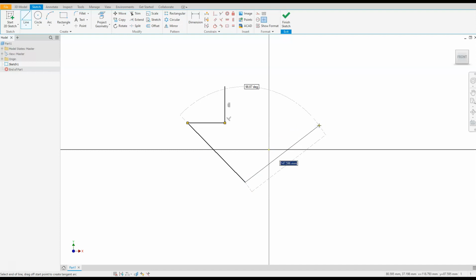And this is one of the things that will get you in trouble anytime you're using these 3D programs: if you get close to other things, you've got these constraints that are locking up. For example, this is trying to put a perpendicular constraint on that. Well, I don't want that to be perpendicular. So I make sure I just rotate that away. I'll do a left click, and I'm also going to make sure that I'm not in line with any of these other points, because sometimes it will lock onto those other points. So I'm going to make sure I avoid that, and I'm just going to put it somewhere around here.